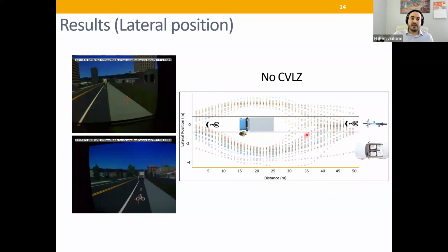I didn't think that cyclists would go use the sidewalk. I thought they would just go in the travel lane. But actually, when I did the beta test, I saw that some of them used the sidewalk. So that's why I had to redesign some elements and do a curb extension for cyclists to make them use that sidewalk. And so we had about 18 cyclists out of 48 decided to take the sidewalk instead of the travel lane.